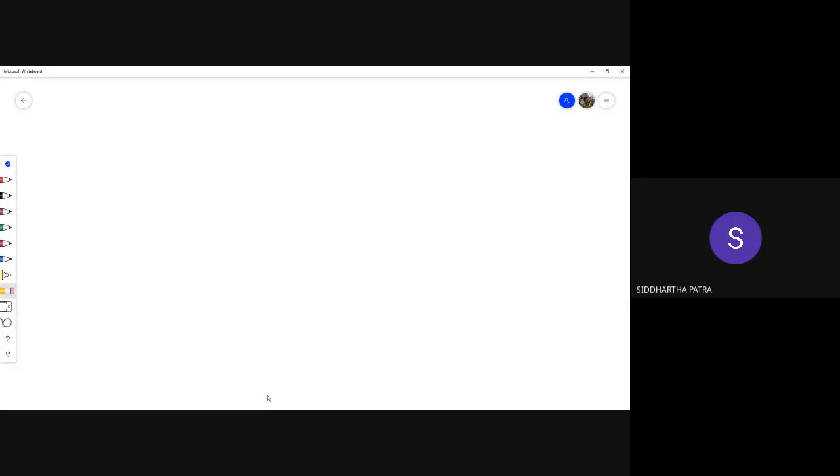So let us now construct our Pascal's triangle. As we discussed earlier, the Pascal's triangle becomes a Pascal's pyramid when you go for three-dimensional elements. So there is xi, there is eta, and up to this, these are the constituents of the shape functions of a CST element.